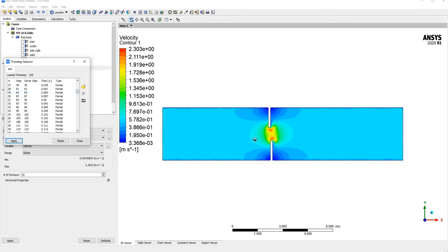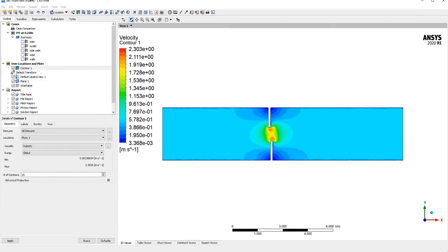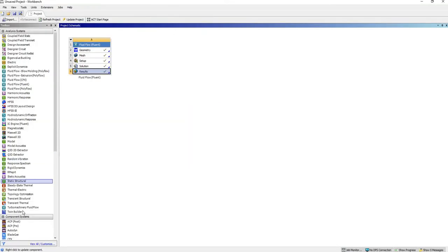So this pressure and velocity and all the parameters, we'll interpolate that to the structural analysis solver, and we will see the deformation of the solid bodies. Okay, so that's how one-way FSI works. No dynamic mesh, not too much complication, and here you can use a static structure. So the applications I can think of are a lot.